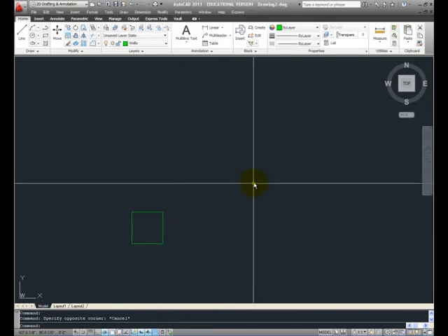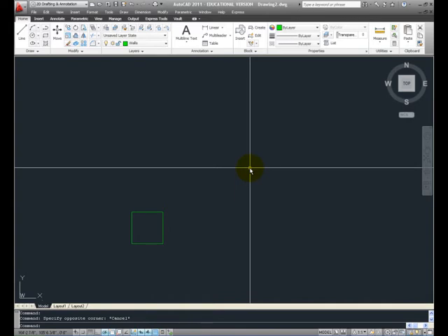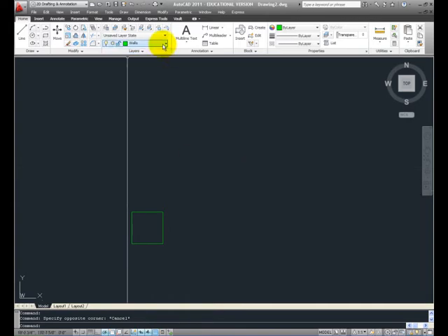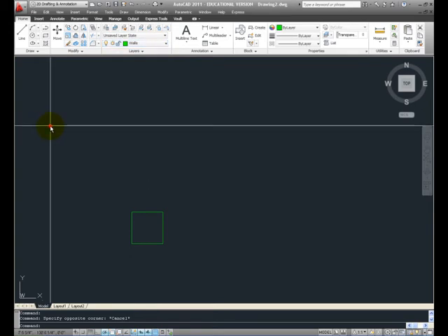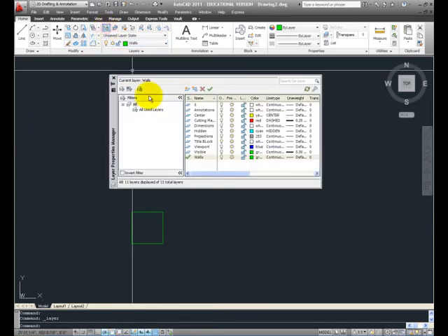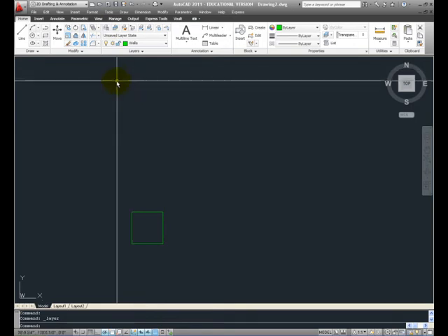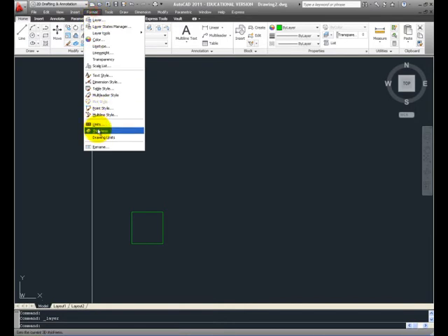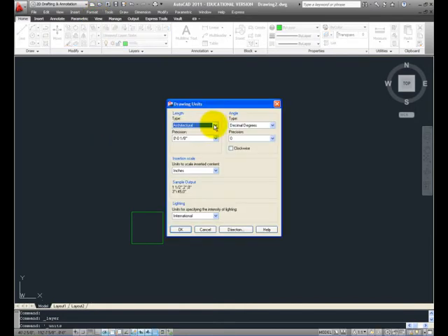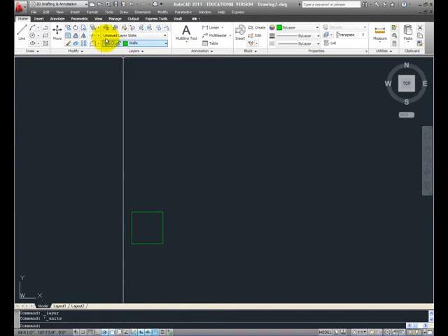This exercise is an architectural exercise. I started out by creating a brand new layer called walls. The properties of that layer are as shown here. The units for this particular project are set to architectural, with the precision and everything else remaining just as you see. So we'll accept all of those defaults.